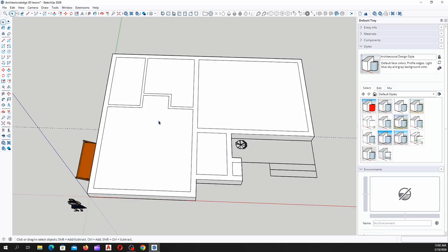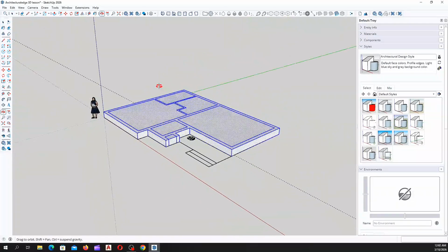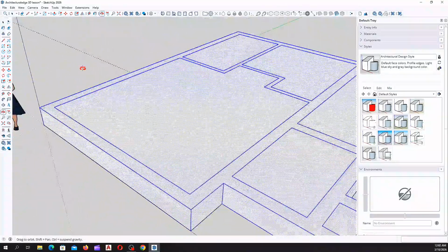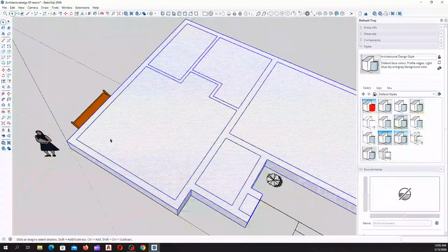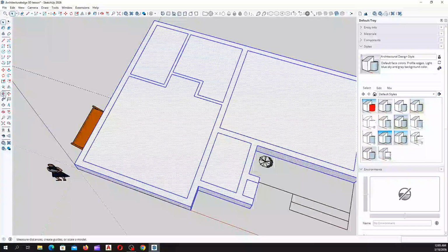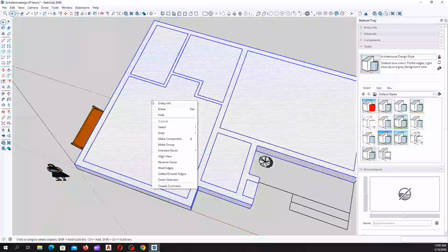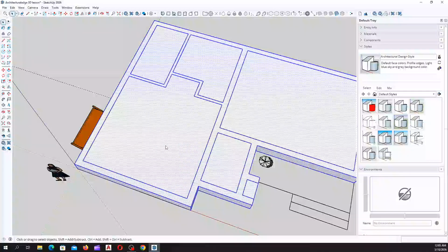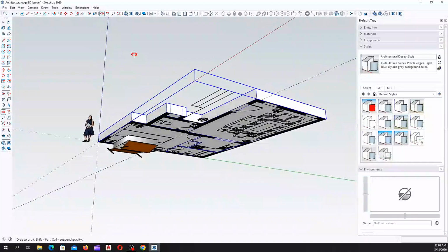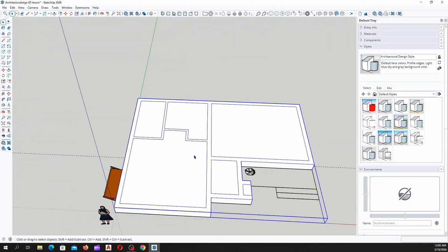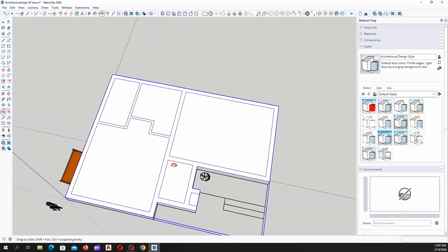If you triple click, 1, 2, 3, it selects the whole drawing on the workspace that is connected together. So now you right click after you triple click, then you come to this on our drop-down menu. You can see Make Group. So you click Make Group. Immediately the whole of this entity on our workspace becomes a group.